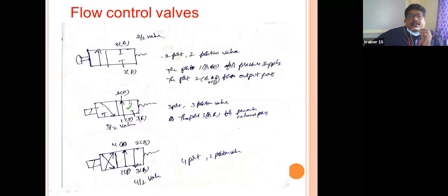This is the initial position, when the solenoid is not energized. And this is the position when the solenoid is energized. That means here the changing, if you see clearly. See here, when the pneumatic power supply or hydraulic power supply is given to the system, for example a single acting cylinder, that is a linear actuator, if you give the power supply, so what happens? It pushes the piston, right? And see here, the reservoir is cut off, it went to atmosphere.